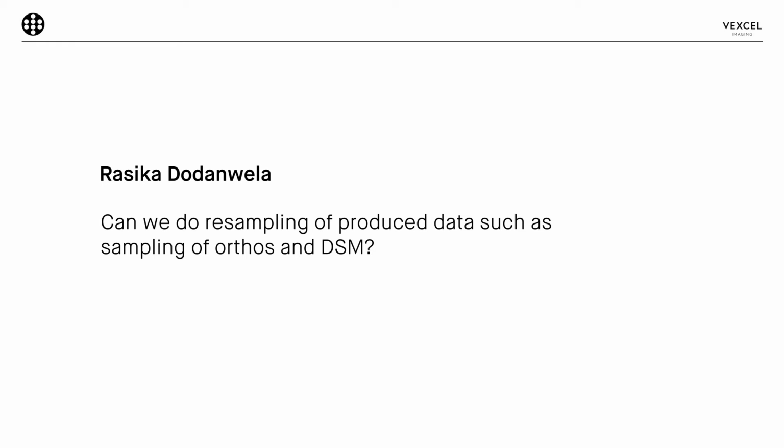Can we do resampling of produced data, such as sampling of ortho and DSM? In my understanding, the answer is no, but again, Bernhard, please weigh in for that question. Yeah, so for the processing, we are using the imagery as it is available for the input to the project. But when exporting the data, we provide some flexibility to configure the DSM and the orthos. So if flying, let's say, with 10 centimeter ground sampling distance, you could export the data at 20 or 30 or whatever ground sampling resolution.